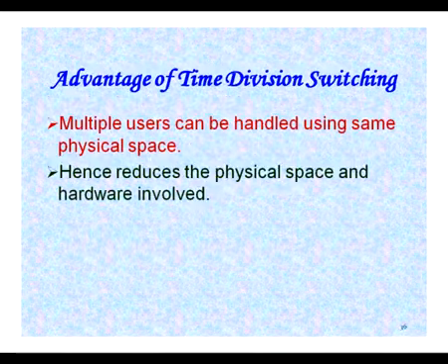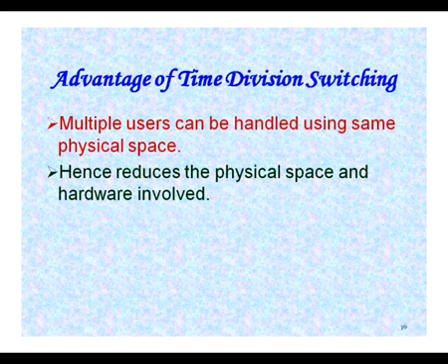So the advantage of this time switching is that multiple users can be handled using the same physical space, and so we can reduce the physical space as well as the hardware involved, because now we don't need that many wires physically present, but just a number of memory locations which are sending data from one point to another.